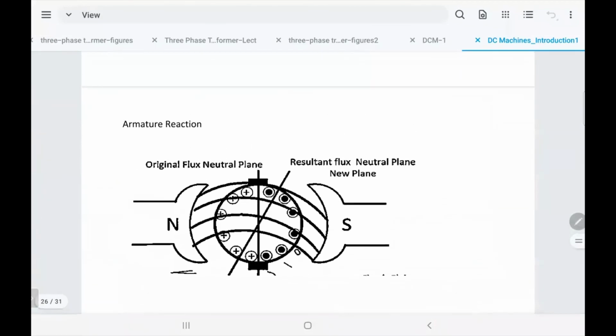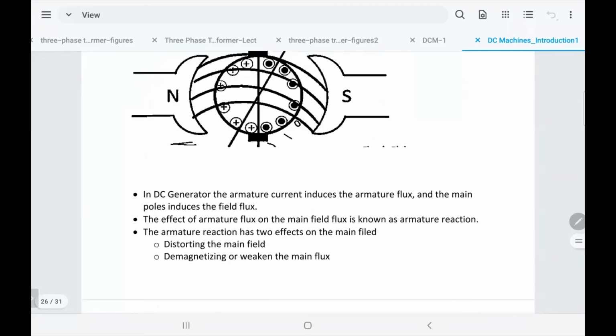That's what I explained to you, that you see the magnetic field will be bent, that's the distortion. You are expecting that the EMF will be zero at the brushes. No, it's shifted. So actually, it will be zero along the other axis. That's what's called spark.